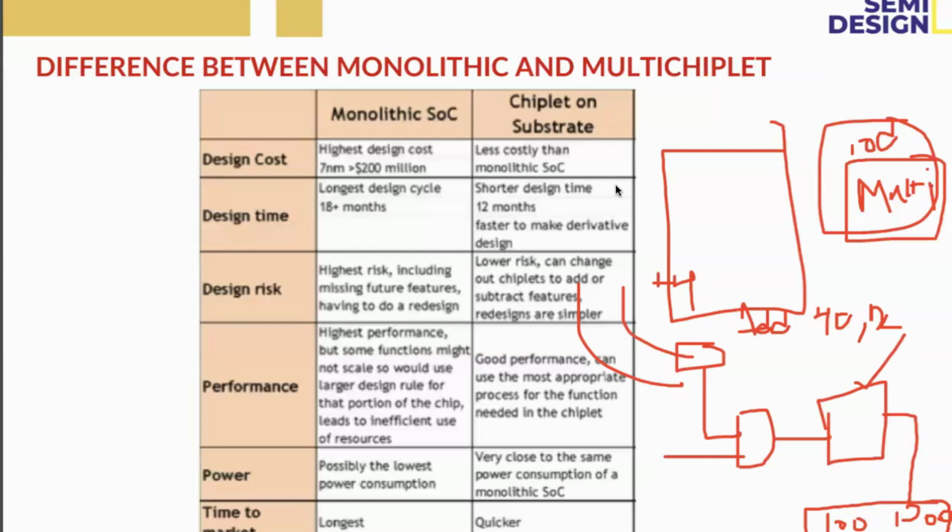Like that, if you go to the architecture level, there will be various blocks involved: memory block, graphics processor block, NBIO or SBIO, multimedia hub, different blocks. Everything we write as a Verilog program and generate the RTL schematic. But for a processor, we write the instructions and generate the binary data. Both we need to verify, at the SOC level or the IP level, by using SystemVerilog or UVM.